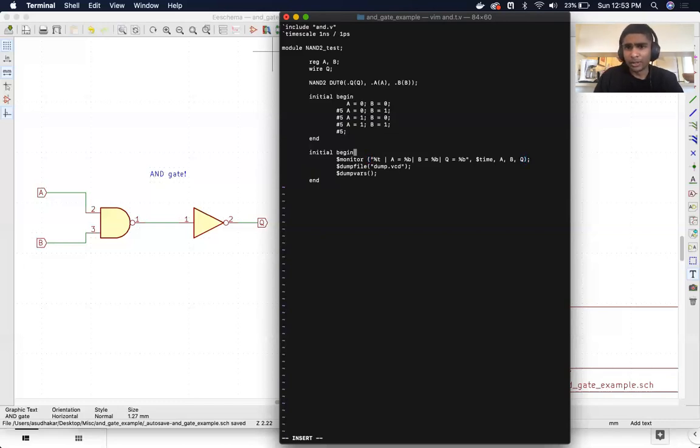You might be saying, all right, you already have an initial begin here. Why are you doing another one here? And the cool thing about hardware is that unlike traditional software programming languages, hardware can operate in parallel. So in your Python script, you're usually going line by line, executing. Maybe you go back up if you have a loop, but you go in vertical order. That's not true for hardware. If you connect a signal to multiple inputs, it'll all fire in parallel. And that's exactly what's happening here.